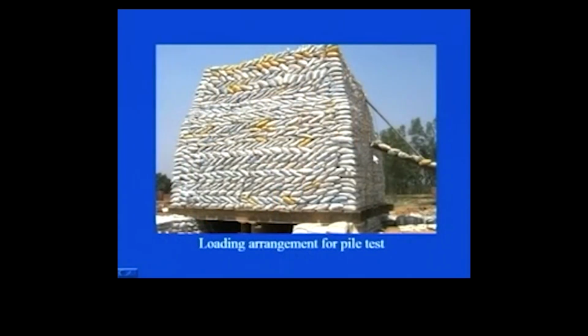Then you see that once they place this first layer, they make an arrangement to go to the top. They just put two bamboo ballis here, put the soil bags on top of that to make a platform, and then they go on putting bags one over the other.